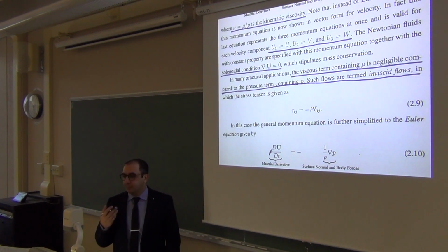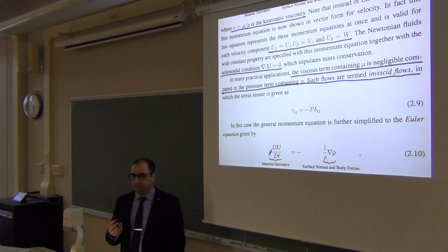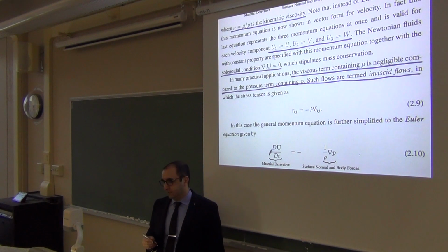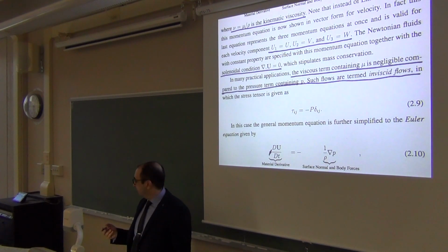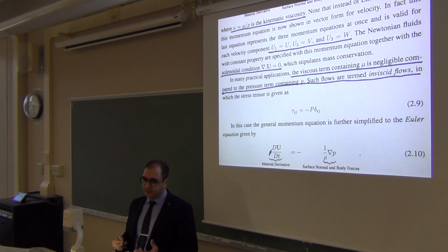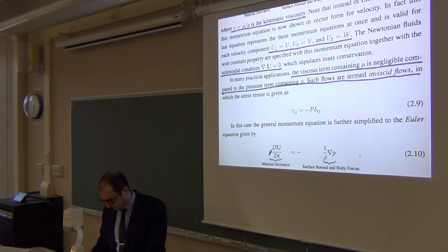Flows in the aerospace domain have such flows, like flow over airfoils at the top of the atmosphere, which is very thin, velocities are high. A lot of those applications, you can assume inviscid flow. It's a very good assumption. Of course, in ventilation science or hydro engineering, that's not a very good assumption, because water is very viscous, and high pressure air, like we have it here near the Earth's surface at low velocities, is very viscous. But up there, fast velocities, it's a very good assumption, inviscid flows.